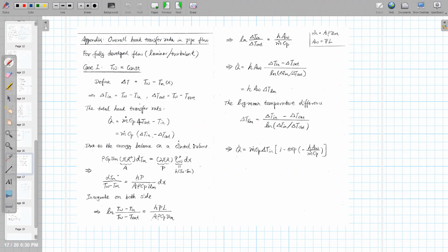The problem is that you do not know the outlet temperature because it's affected by this q_w double prime value, right? Affected by how much heat we get from the wall. Okay, but you can rewrite this as m dot Cp times (delta T_in minus delta T_out). This one minus this, because you simply cancel this T wall here. You still get the value T_out minus T_in.